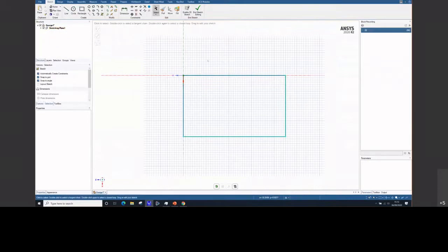To actually highlight and show your constraints, you have this little blue I button up here, so this will show your constraint tips, and then you can click these drop downs, and you can basically see the actual constraints that you're using. Another thing you can do is you can click on the actual lines themselves. You'll get this, and you can actually remove constraints if you wish. So you can see, obviously, this is a constraint there that's locking to that point. If we didn't want it to, we can remove those constraints literally just by deleting them, by clicking on it here.